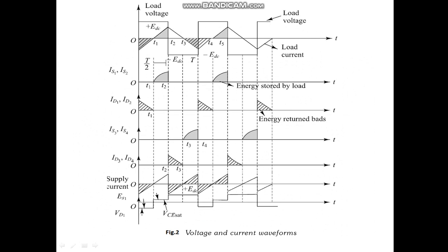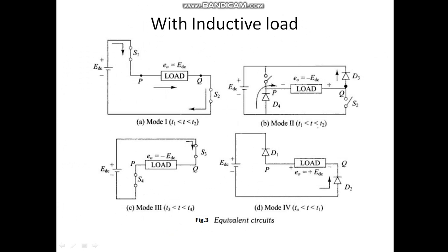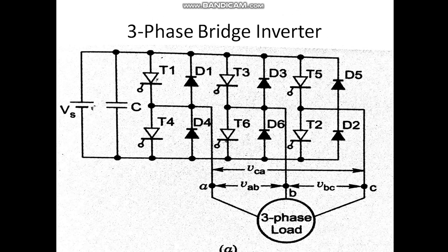See here, the current will move, but the inductor will slowly get discharged. See, the stored energy is dissipated. So up to this point it will be completely discharged, and from here it will change direction because the source will take the lead. Till here it will be in the opposite direction. At that time again, through the switches the inductor gets charged, and through the diodes the inductor gets discharged again. From this point, again through the switches the inductor will be charged, then discharged. Similarly we get a sinusoidal, meaning triangular wave. Somewhat I can say sinusoidal. So this is a single phase full bridge inverter.